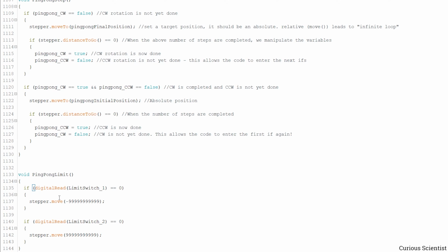So what we did is that this function runs with every iteration of the main loop. And then what it does, it comes in and checks if one of these conditions is fulfilled. And this simply does the following. Whenever you press one of the limit switches, we flip the direction. And of course, the most important thing that we have to take care of is whether your limit switch value becomes 1 or 0 when you press it. So you have to check this.